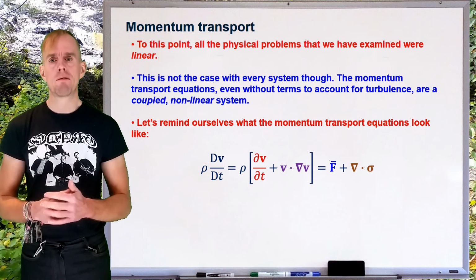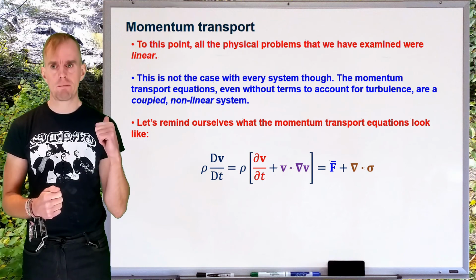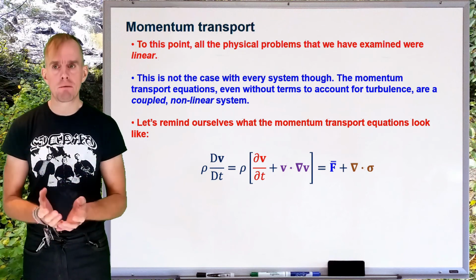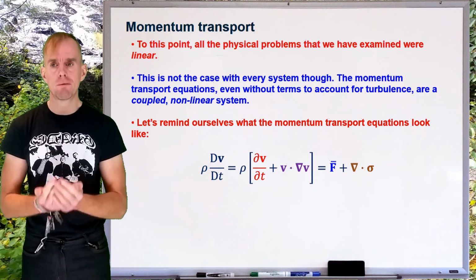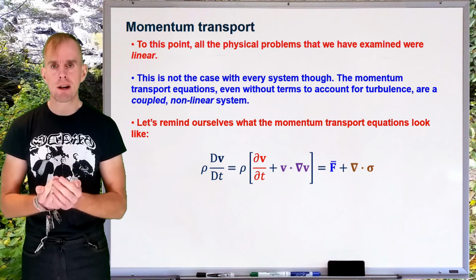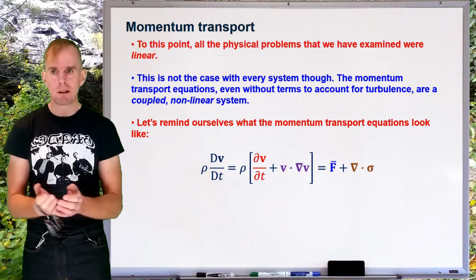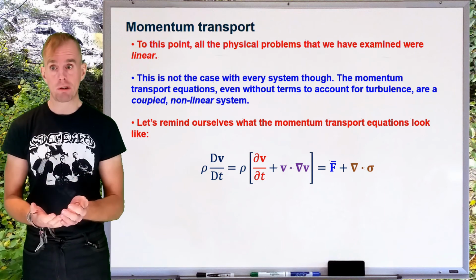And so when we write our forces here in F bar, we have to take special care that the way in which they're written includes that per unit volume term. It's a rate of change of volumetric momentum, don't forget. So F bar are in effect volumetric forces.